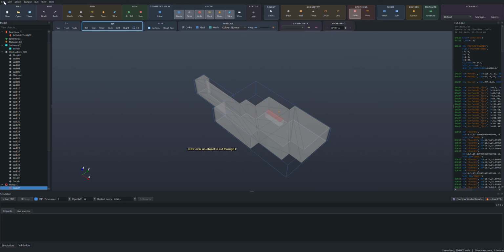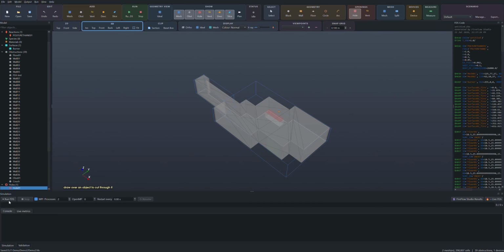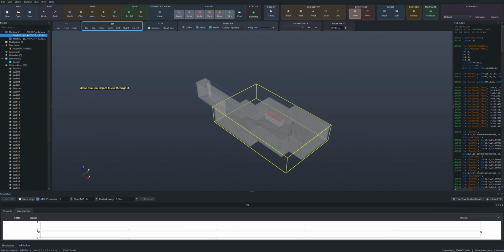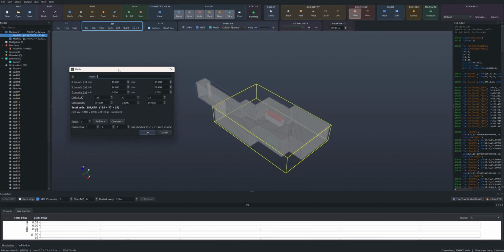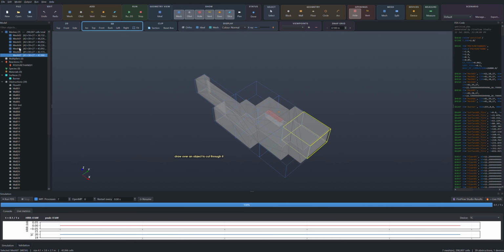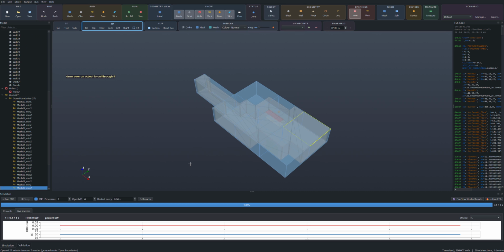Once you've saved it, let's say save demo 2, and let's call that demo 2. Okay, you can then run it straight from here. It's going to automatically detect, oh, you know what? I did not show you one of the best features, and that is if you choose this mesh, you can easily split that. Let's say 3 columns, 2 rows. There we go. And most crucially, open your mesh boundaries.